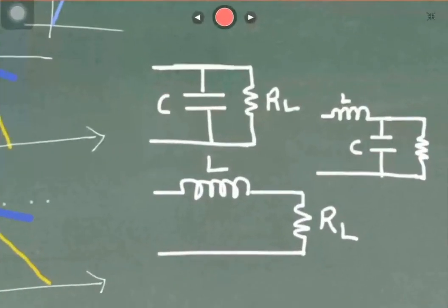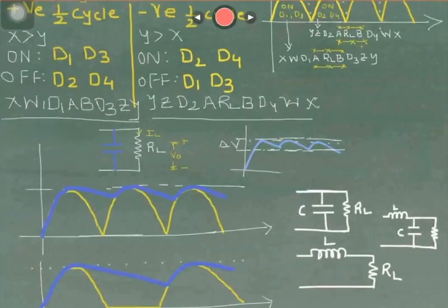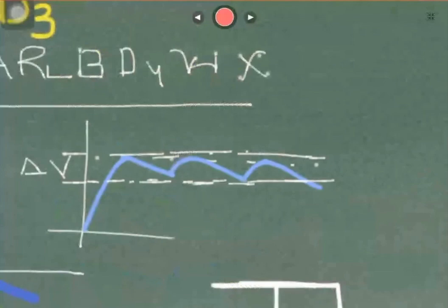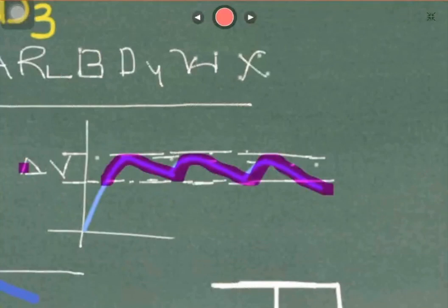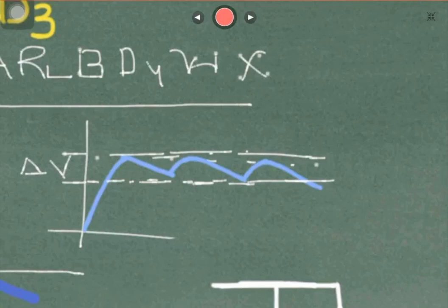So we will see how the filter circuits work. Just to give you a clear elaboration of what I was talking about, if you see over here, we have implemented a filter circuit, and the variation has been given by a number delta V over here. In our previous case, the variation was from 0 to Vm, but now when you apply the filter circuit, it is not from 0 to Vm, it is delta V. How this is achieved and how it will improve the ripple factor, that study we will do in the next lecture.